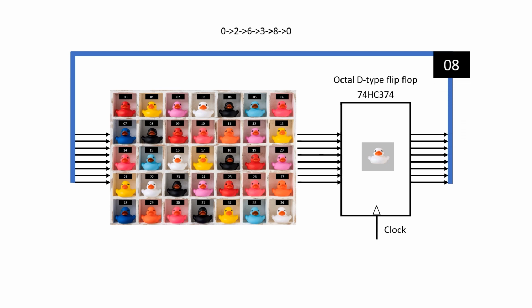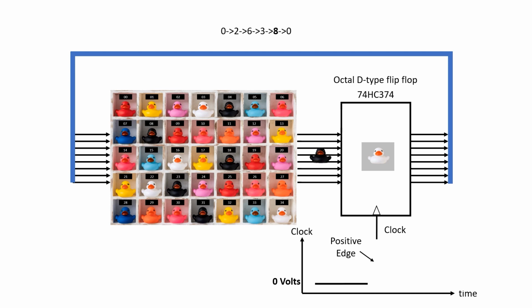Now I want you to think for a moment how we might be able to use a circuit like this as a raster generator. It certainly is much simpler, and it'd be nice to avoid all the counters with the AND gates and OR gates. Remember that the high-res image starts at location 2000 in hex. Let's say we have some sort of mechanism that puts us at location 2000.